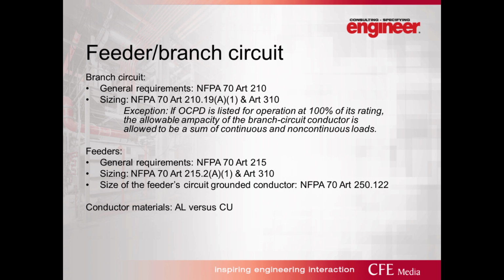However, aluminum has a better capacity per weight. Depending on application and the project priorities, whether it is cost, schedule, or quality, the engineer will pick the material of the conductors to make sure that the client's expectations are met. In most of my projects, we provide copper throughout the building. I do see aluminum sometimes from the medium voltage utility transformer to the building switchboard or switchgear. Some critical applications, such as hospitals, may not even allow aluminum on the project.